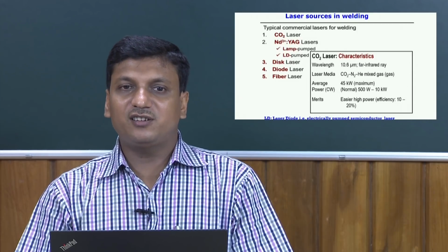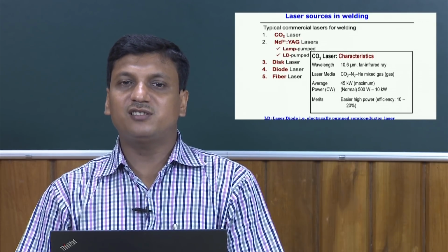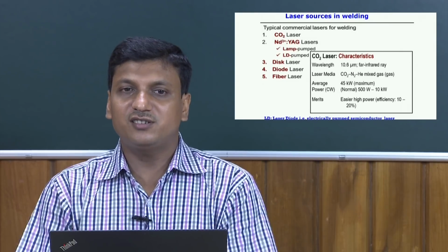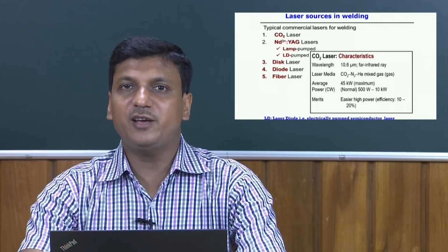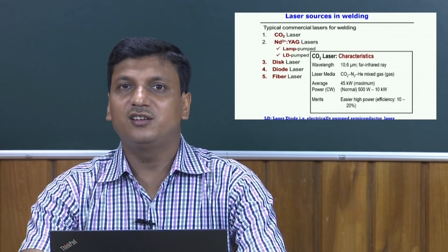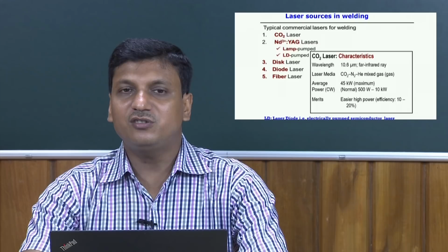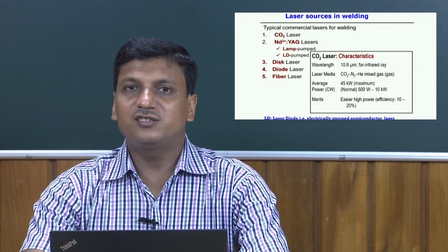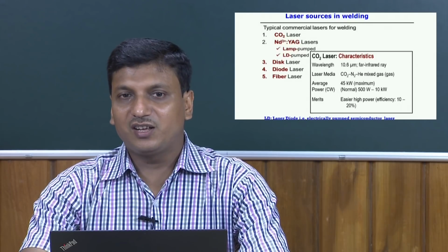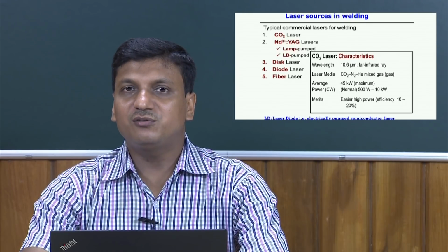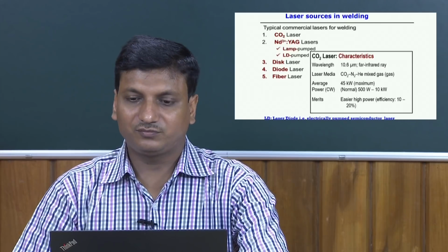The disc laser, diode laser and fiber laser also have certain advantages, but nowadays if a high depth of penetration is required with a very narrow heat affected zone, then the fiber laser is a good solution. Disc laser and diode laser are used for some other purposes.